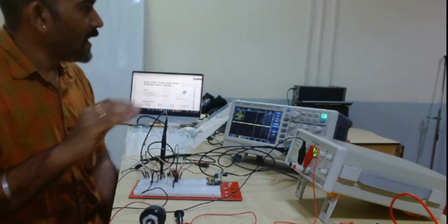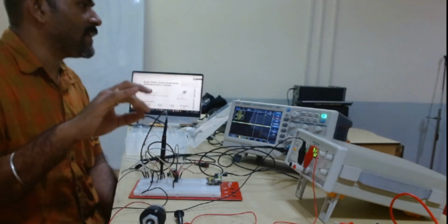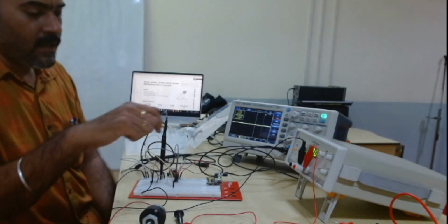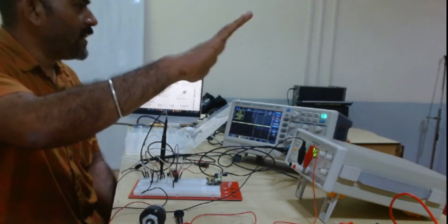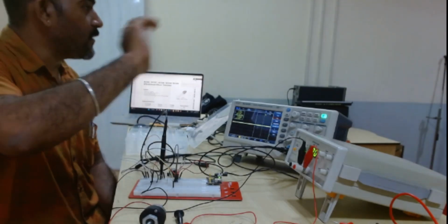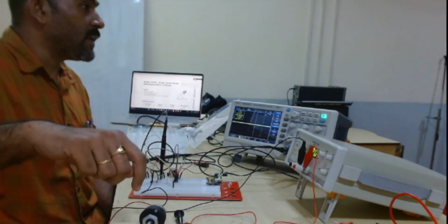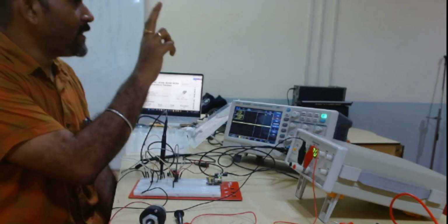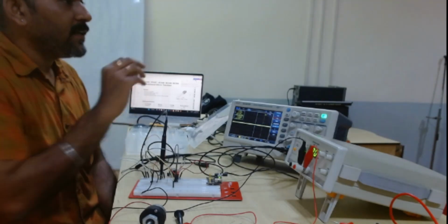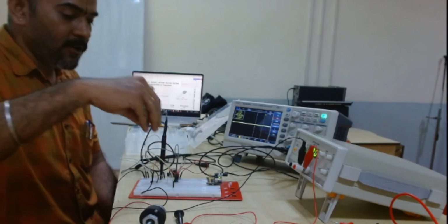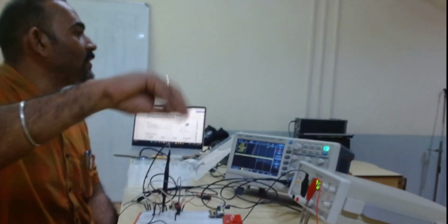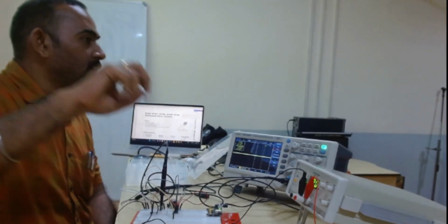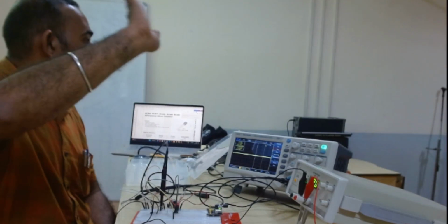I mean you have understood how to make the connection and how to make the circuit work. Now here we have done 2 parts actually. First thing is the monostable we have connected, it works fine. It is working at a particular voltage and we have made the motor run because of the monostable. Second part, if you see, I am working in 2 voltage domains now. One is the 5 volt domain, the other one is a 12 volt domain, and your timer is in a way isolated from 12 volt, not completely but to a certain extent, because the timer just drives 5 volts to the base.